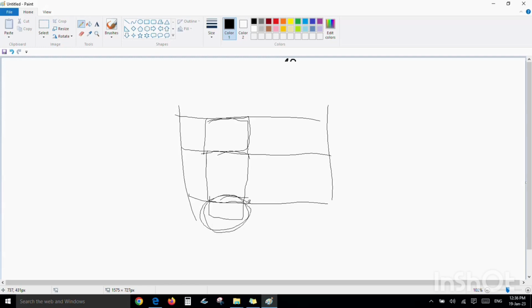This is a notch, the extra part which is there, that is a notch that shouldn't happen. And macro density, how much space area it is occupying. And cell density, we check after placement. And legalization, whether it is snapped to grid. Legalization is nothing but snap to grid only.